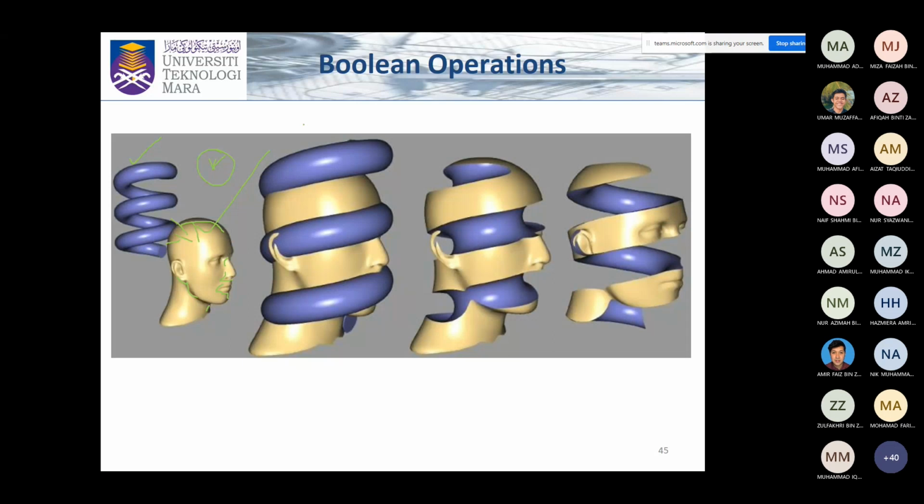To model this, it's not possible. Of course, you can model, but to get it accurately according to this particular head, like I said, model my head, you will not be able to model it accurately. You can only make estimations as you go. But one way to actually do this is, later in the chapter you learn, you can reverse engineer this entire model. That means you can scan the image of the head and bring it into CATIA through digitalization, and you can actually recreate back the surface and then create the solid.